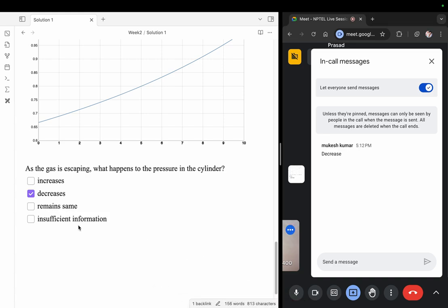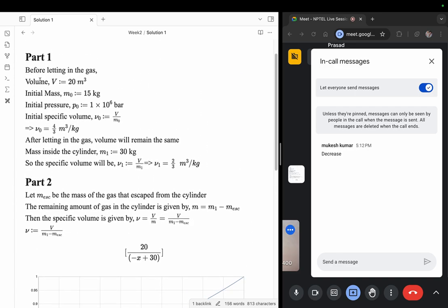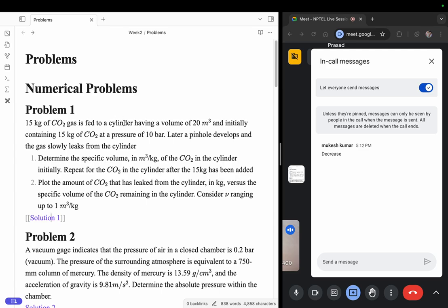Yeah, now coming back to this particular question. Just like what we discussed last week, you will not be able to comment directly on the pressure because you do not know the nature of heat interaction. In this question, nothing is specified about what happens at the boundaries for the heat problem. Is it adiabatic or isothermal or something of that sort has to be provided. Only then you will know what to do with the Q. Only then you should be able to say what will happen to the final pressure. So without specifying the particular process, you should be saying that the information is insufficient.